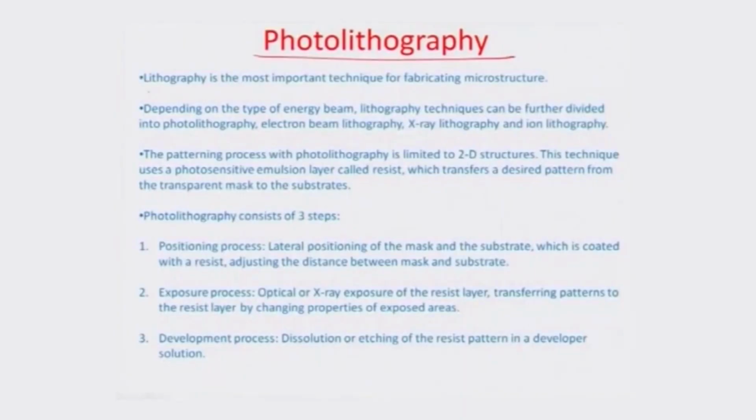It is definitely the most important technique for fabricating microstructures, and depending on the energy of the beam, lithography techniques are divided into photolithography, electron beam lithography, X-ray lithography, ion lithography, and so on. As is obvious, if you use light waves for lithography, it falls within the domain of photolithography. If you increase the beam energy, it falls within the domain of e-beam lithography, X-ray lithography and ion lithography. Ion lithography you can increase up to any extent by accelerating the ion using an external electric field.